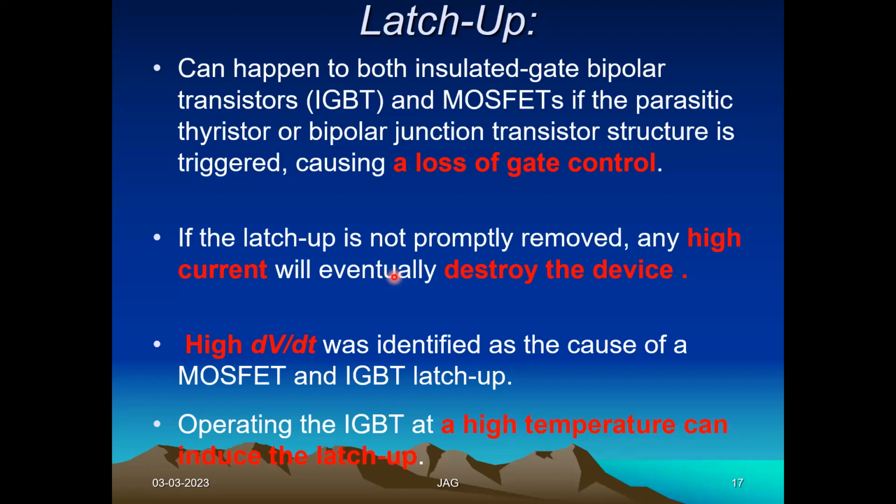What will be the side effect? A switch which is supposed to be turned off is still conducting. At the same time, another switch by nature will be turned on. Both these switches being on will create a dead short circuit across the supply. As a result, the entire path experiences huge short circuit current, which spoils the show. Even the PCB will be burned, and even a fire may break out. You must have read the news recently.